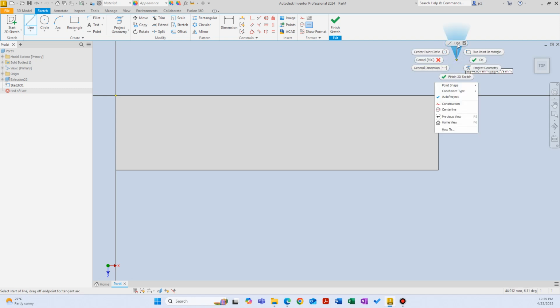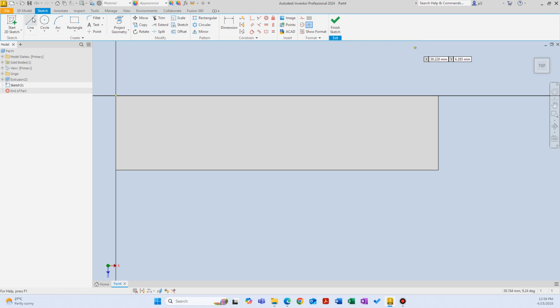So as I click on the line option, as my create line is active, as I hover on this horizontal line, notice that Inventor highlights that line with bold black color, which means that Inventor understands that I want to take advantage of that edge in my new sketch. So I am creating a line here, and again, touching this vertical line, and now Inventor understands that I want to use that vertical line as well, and I finish my line. Now, as I get out of the command, notice that horizontal and vertical lines are highlighted with yellow color. I didn't have to draw 3 lines. I took advantage of existing geometries. Now all I have to do is dimension it.